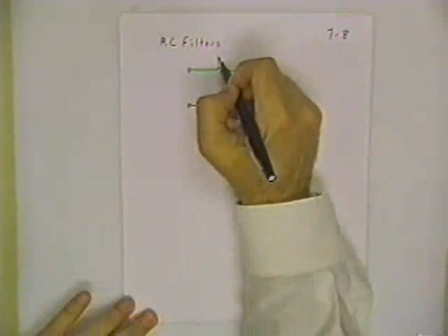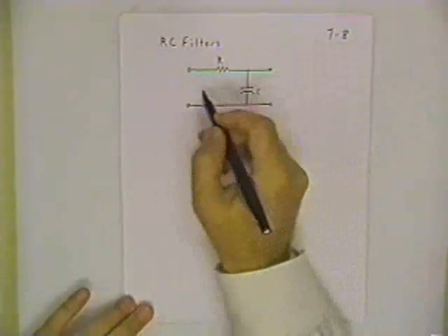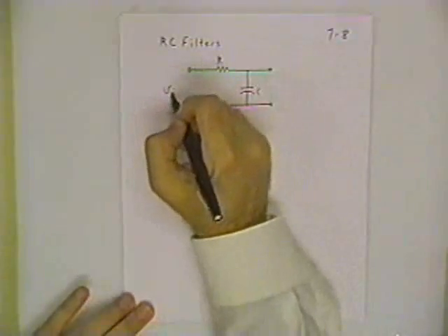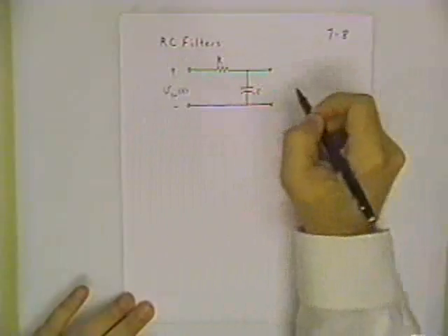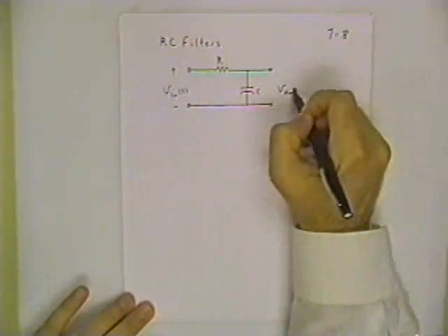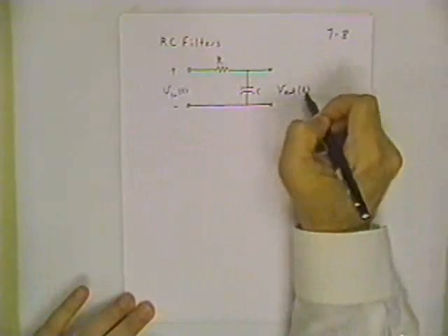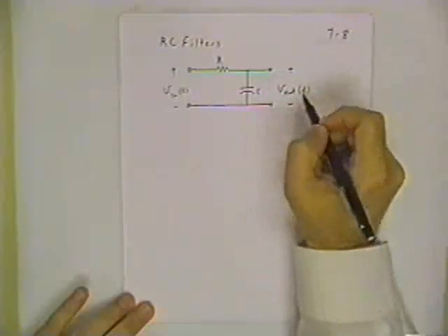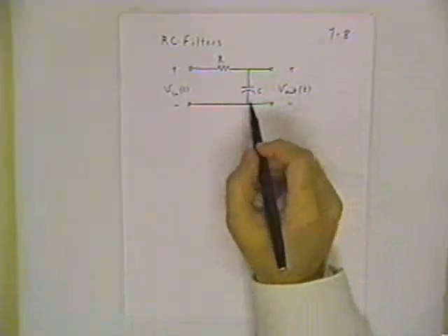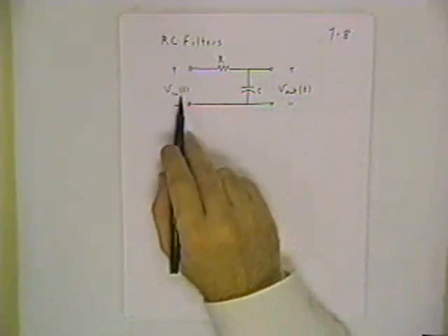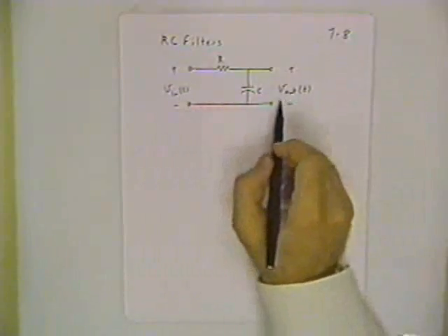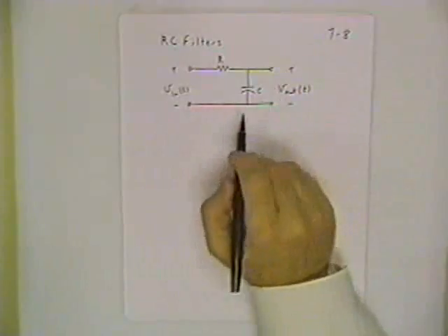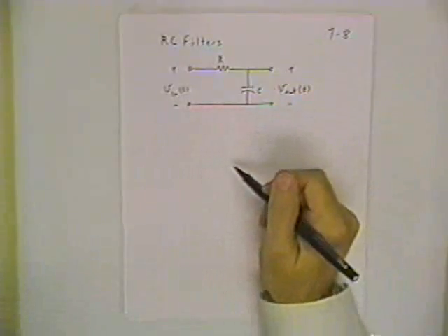But now we're more interested in how this circuit responds to different frequencies as I take the input sinusoid and compare it to the output sinusoid. So you have to imagine that you're looking at this on an oscilloscope. And then let frequency increase. Start at 0 frequency and increase through larger and larger frequencies, and ask ourselves what happens to that output waveform.